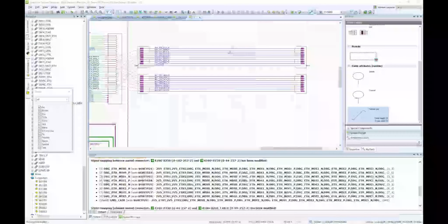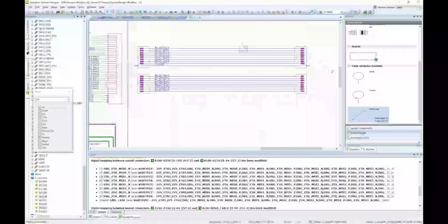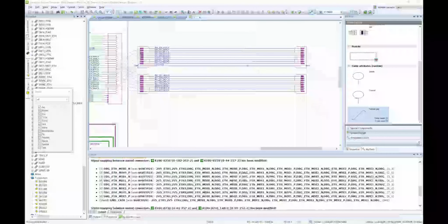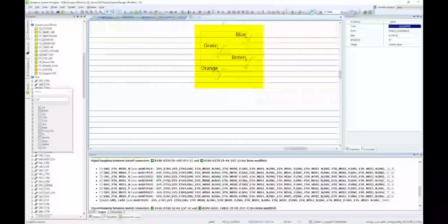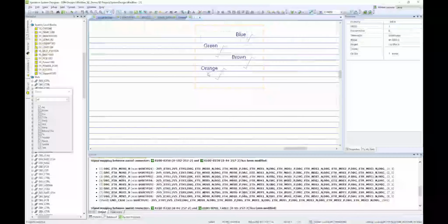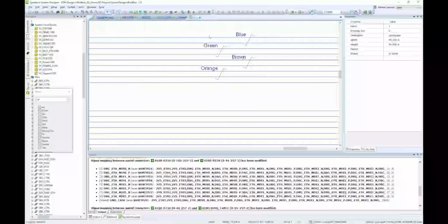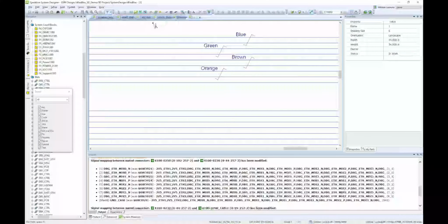Ethernet wires are twisted, and the System Designer section of My Parts has built-in decorations for representing a twisted pair. Simply place the decoration on the desired wires. After all four decorations are placed, name them to reflect the correct twist colors.